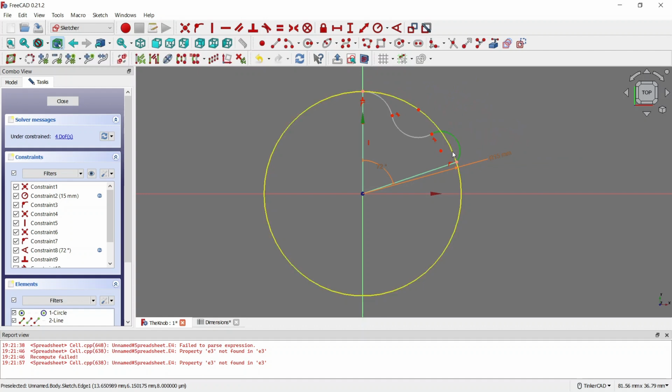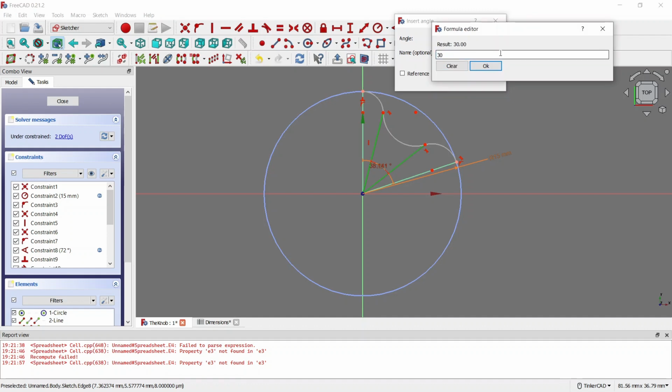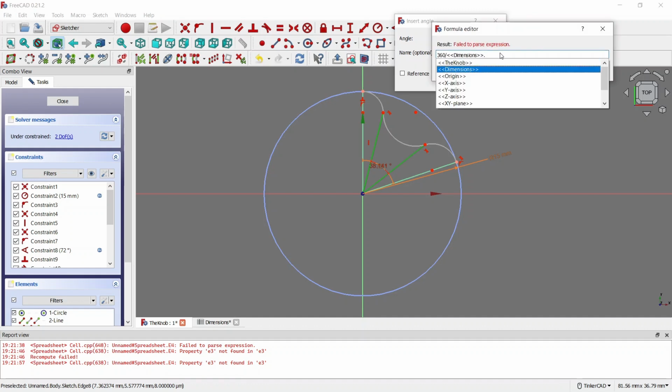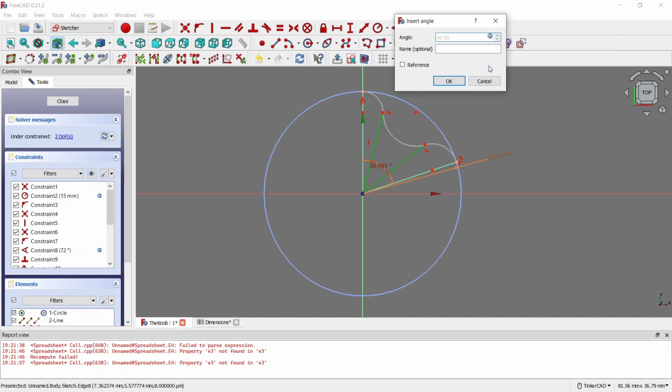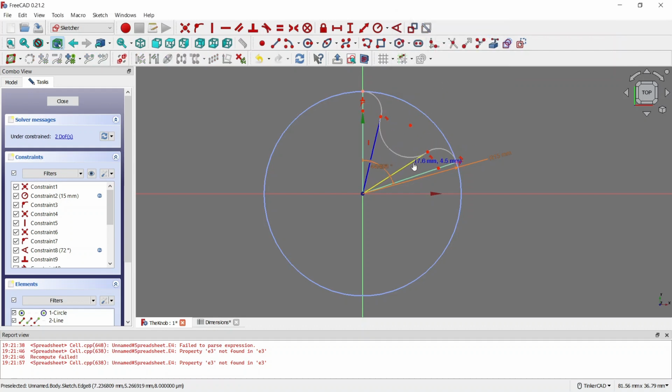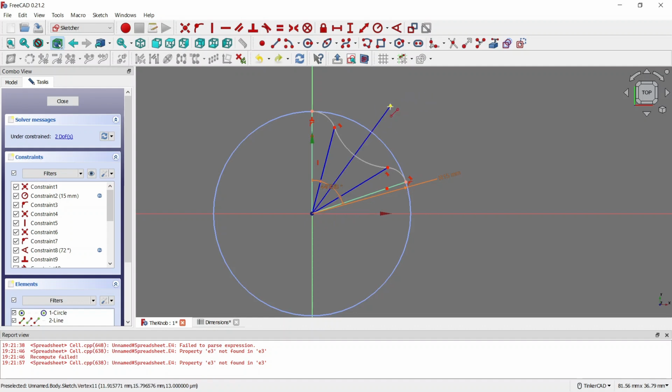and the outside arcs of the wing, I'll constrain them as coincident with the outer circle. The smaller arc will be constrained by those 2 lines, where the angle would be again the total angle of the wing we are drawing, multiplied by the golden ratio parameter. And the last thing we need to do is to have those arcs symmetrical.